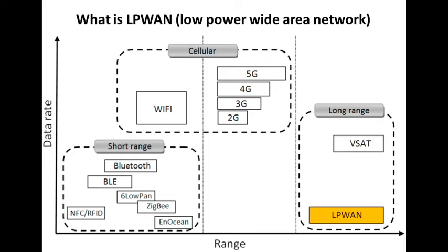They are the short range, long range, and the cellular. In the short range group, there are Bluetooth, Zigbee, NFC, and others. Usually, the coverage is around 1 to 3 meters. The data rate is under 255 kbps. Generally, they are used in home or building automation.